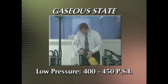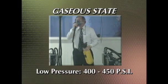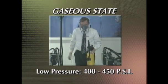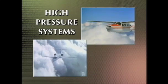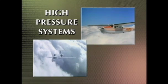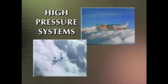Gaseous oxygen can be stored in low-pressure containers at the standard pressure of 400 to 450 pounds per square inch, or in high-pressure containers at 1,800 to 2,200 pounds per square inch. Primarily high-pressure systems are used in both commercial and general aviation.